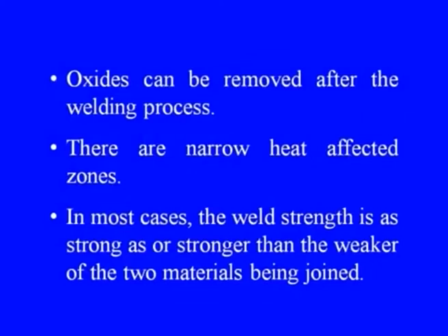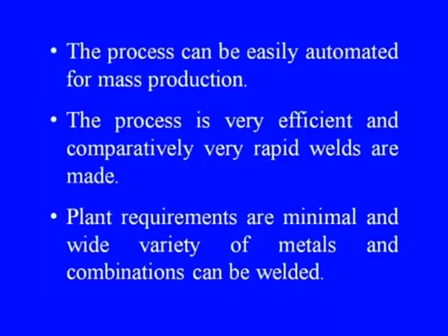In most cases, the weld strength is as strong as that of the weaker of the two materials being joined. This is another important aspect. The process can be easily automated for mass production. The process is very efficient and comparatively very rapid welds are made. Plant requirements are minimal and a wide variety of metals and combinations of them can be welded.